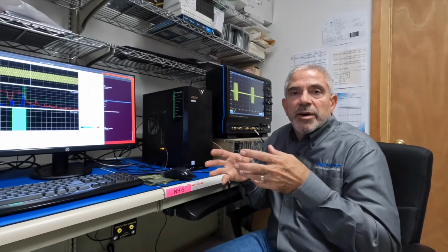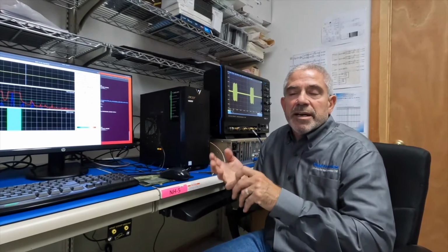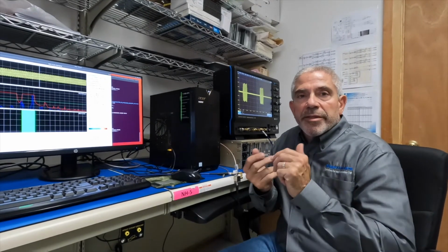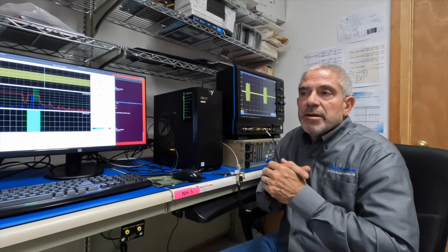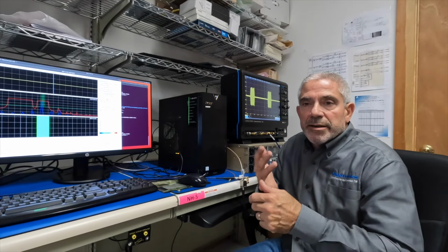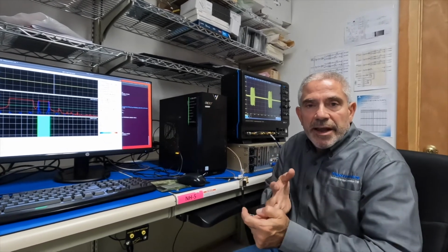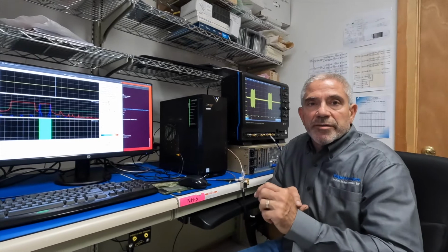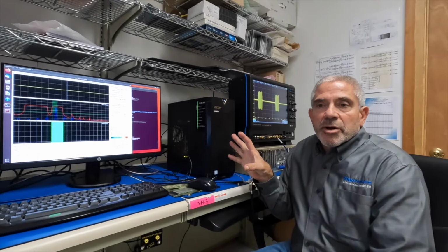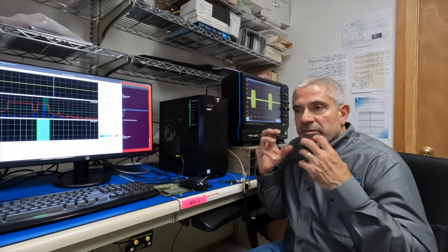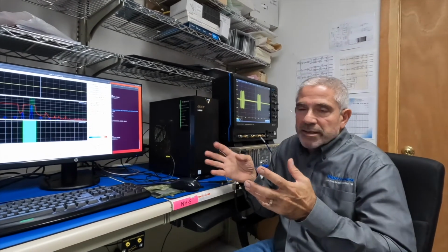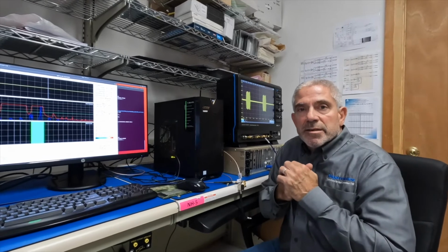None of those systems can do anything without the inline digital signal processing done in real time and the ability to figure out what it's being illuminated by, whether it's radar returns for a radar, or jammer input like multiple range false targets, or whether it's an EW system, say a radar warning receiver, whether it's being searched, tracked, actively engaged, or possibly even in the terminal mode of an engagement with a high PRF waveform. So the ability to do this in real time on the hardware we've shown you, to build a test system around that, to have a real-time closed-loop entity inside your hardware-in-the-loop testing is really important. And that's what we're providing today, the open architecture hardware and software to allow that to happen.